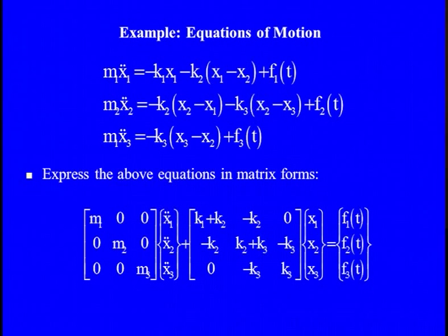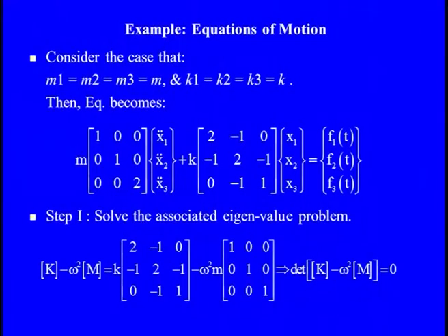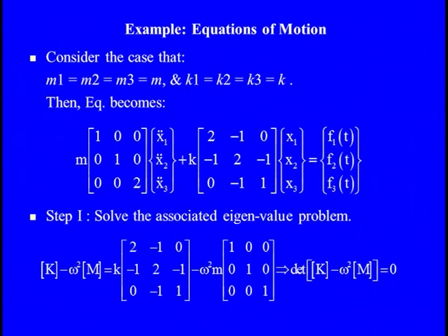So, we have minus k3 and k3 here, and these x1, x2, x3 are the relative displacements of the individual masses m1, m2, m3, and f1, f2, f3 are the forcing terms. Now, say the mass is the same, just a general case: m1, m2, m3 is just one mass m, and the same spring is used, with no change in properties, dimensional and material, and at the same time no other forces act on these springs, just linear forces along one direction only.